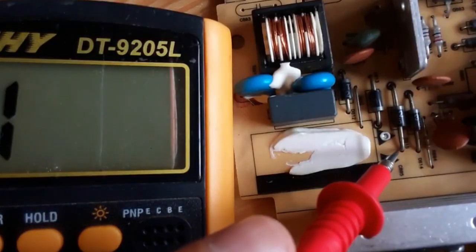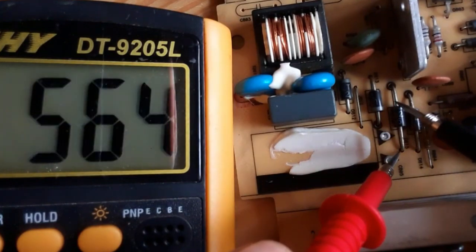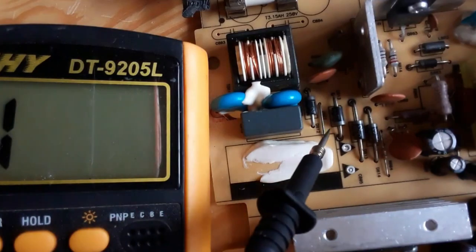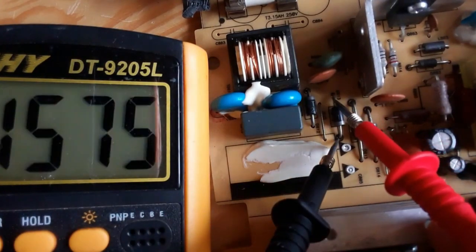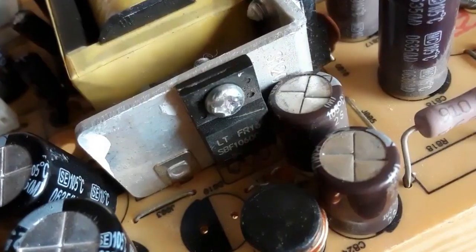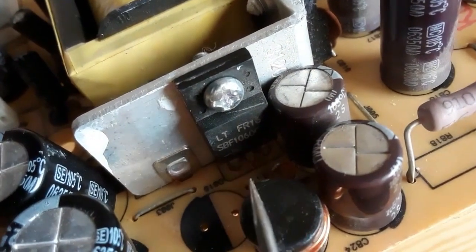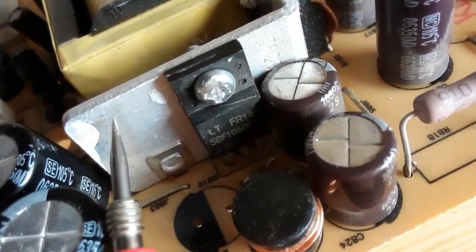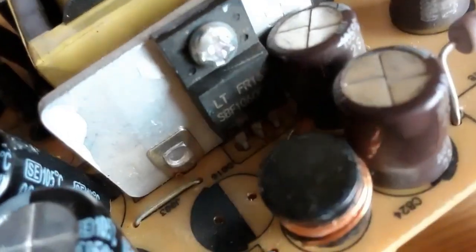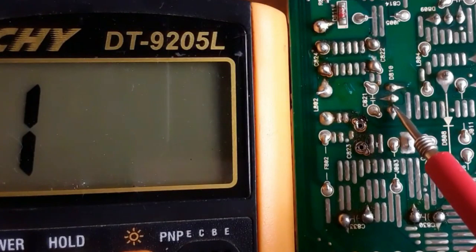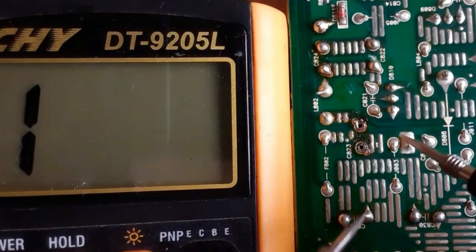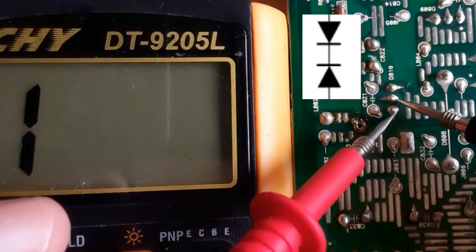So let's check these normal diodes also. We have about 500, the reading or the drop voltage. Let's check the second one, the same, about 500. This is a high drop voltage basically, but if we check this one, the Schottky diode with 3 terminals or 3 leads, we should find a low drop voltage. Here we have its terminals, as you can see in the back of the motherboard. Okay? Basically it contains 2 diodes inside it, so we're going to check 2 diodes.